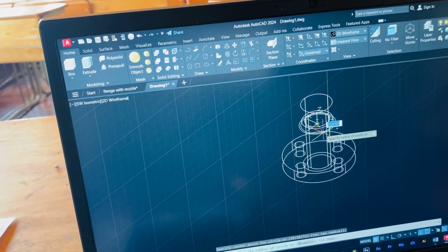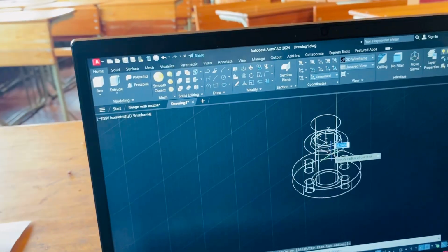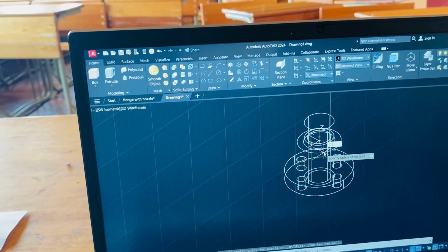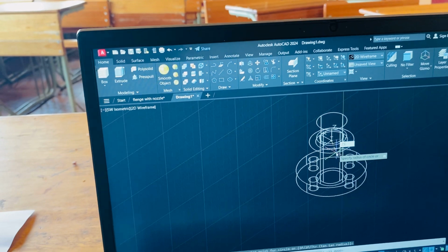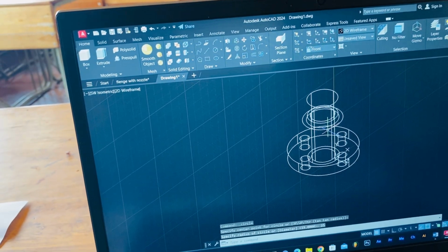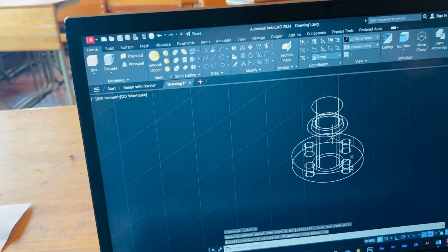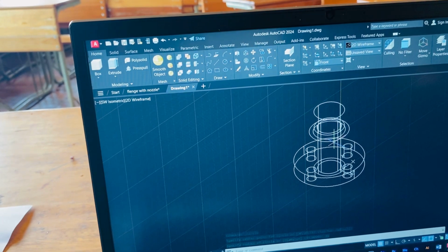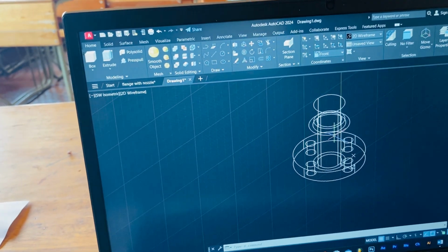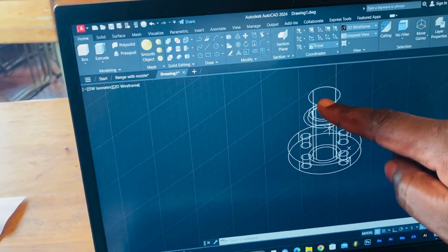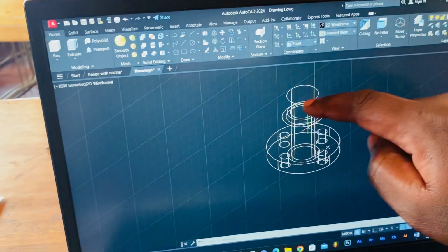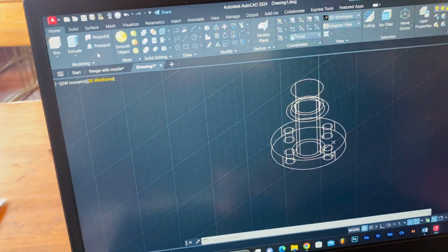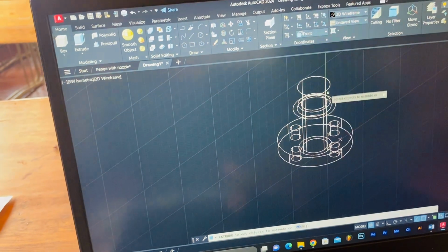Now I think this circle is in line with that one of what? That one of 40 something, and this one is 25. It's in line with that one, and then I extrude it now. By how much? By 30. It must go up by 30 so that it remains on the same level with this one. And then let me extrude it.